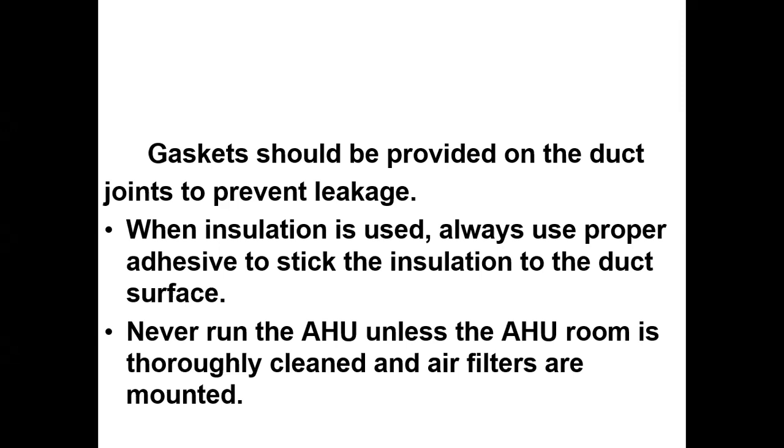Then, while using insulation, a proper kind of adhesive should be opted. Otherwise, eventually the adhesive loses its power and the insulation may fall off. Then never run the air handling unit unless the AHU room is truly cleaned and the air filters are mounted. AHUs should always be run with the air filters mounted.